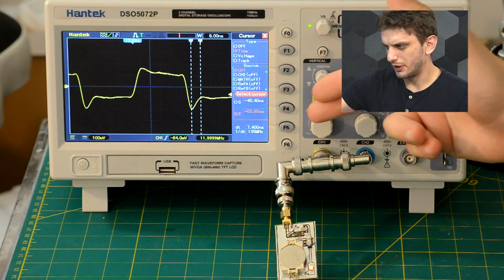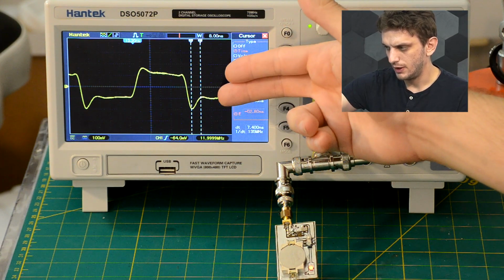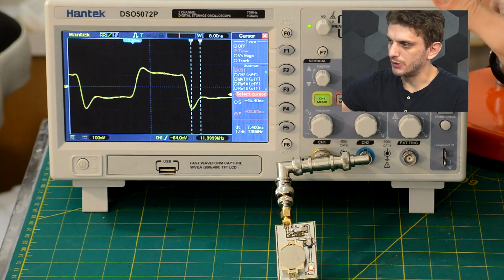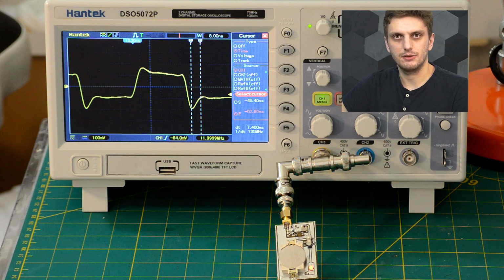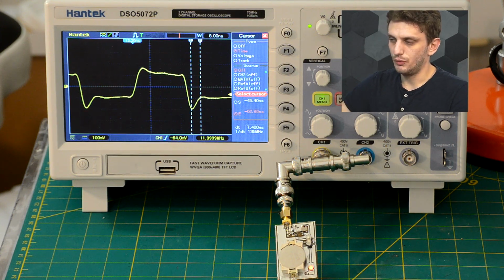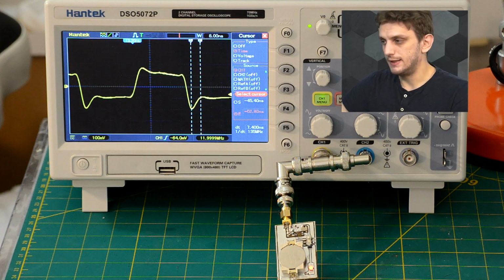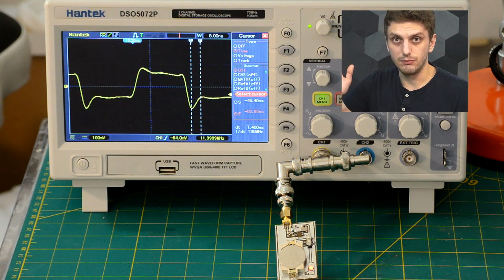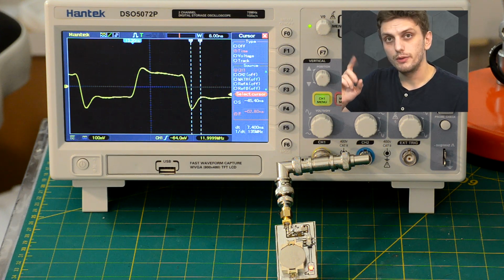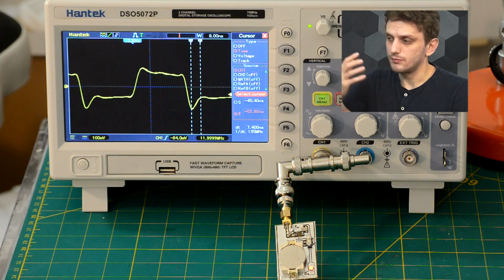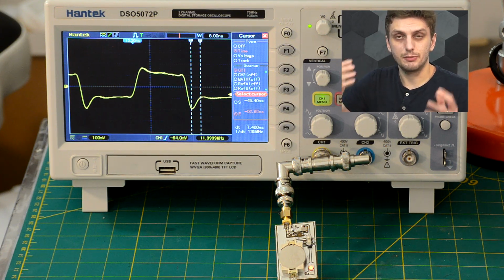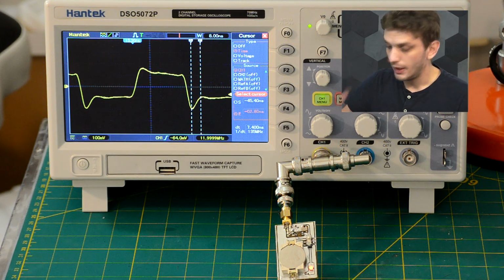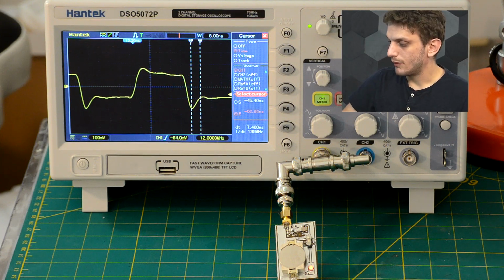So the oscilloscope is measuring about 7.4 nanoseconds of transition time here, but that's most likely because of the oscilloscope's bandwidth limitation. So this is a 70 MHz oscilloscope, and to clearly see what's going on here, this is not the best tool. A better tool would either be a very high bandwidth oscilloscope, so something in the 1-2 GHz range, or a spectrum analyzer, a tool that will actually show us the spectrum of the signal that is coming out of my signal generator. And today, what I'll be using is this thing.